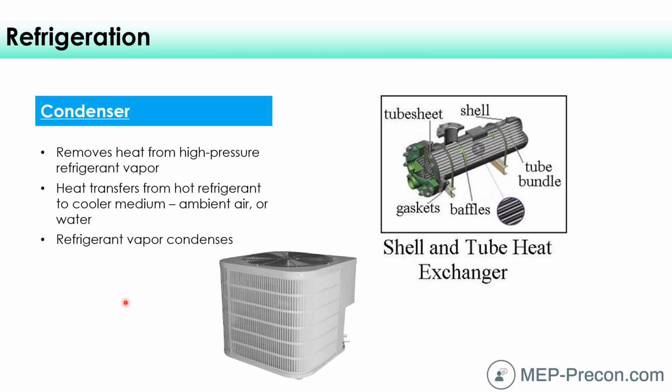Even if there aren't people in there, there might be people working at home requiring the use of those servers, and so a lot of electrons flowing within those IT machines, and so it produces heat, and we need to get rid of it somehow. And so we get rid of that through a refrigeration cycle. So our evaporator might be within that room, that IT room or electrical closet, and it's going to remove the heat.